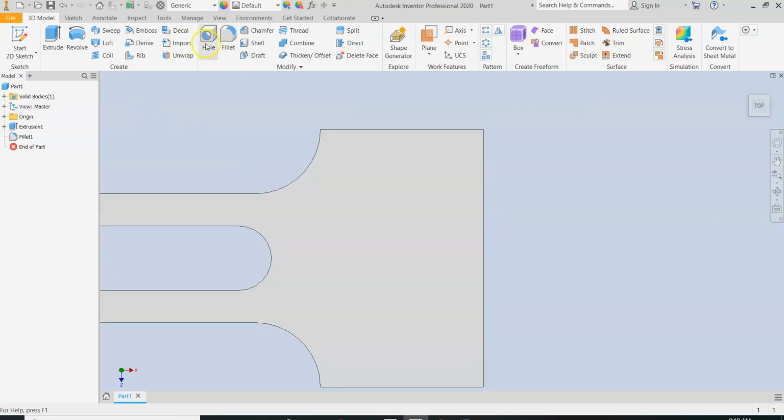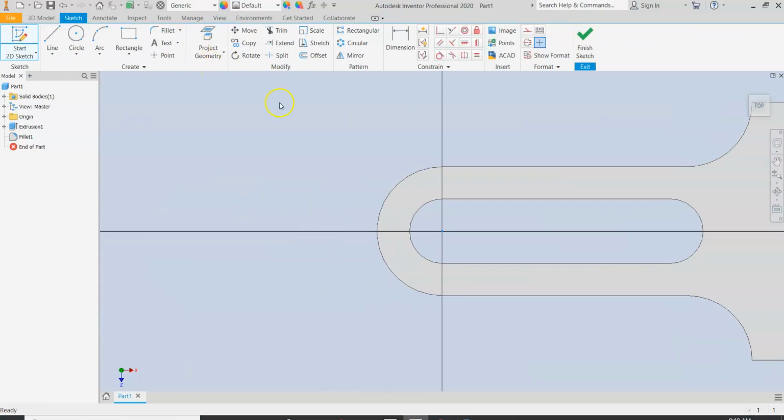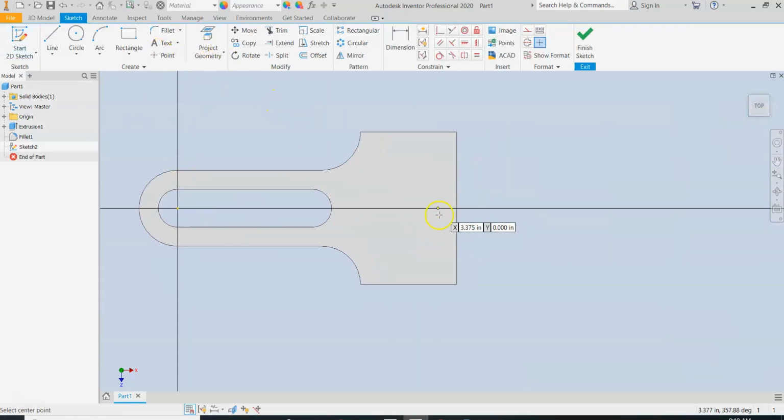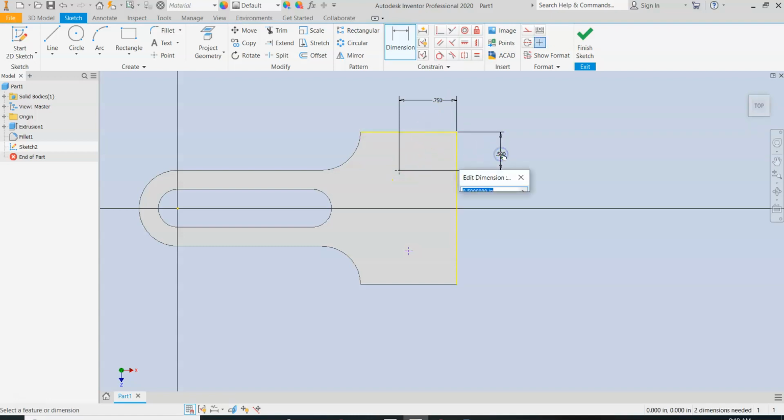Now I'm going to go ahead and put the points on here, locate those points. And because I have two of them, I'm just going to use the point command and drop in 2 points, and I'm going to put a dimension on that point to locate where that counter bore is going to be located. So that dimension is 0.75. It is 0.5 from the edge. I don't know what has happened to my little dialog box there, but my dimension box is not popping up. So this one, the same as 0.5.